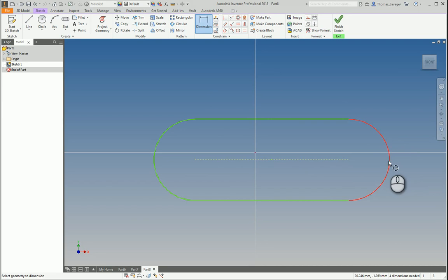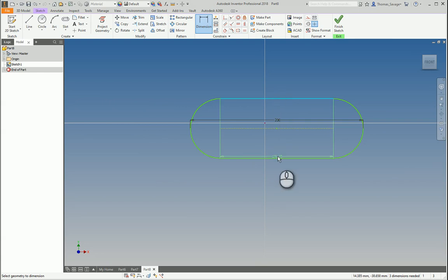If I click on the radius, and then go to nearly opposite, if you follow the line, you can see it's changed to a little dimension tangential onto a circle. If I go down, it changes to the arrows with 2 arrows. If I go up, it changes to that. Click when it's on that, and that will allow you to dimension from the end of the radius to the end of the radius. Very useful. I used to find that it took me quite a while before I actually learned that.